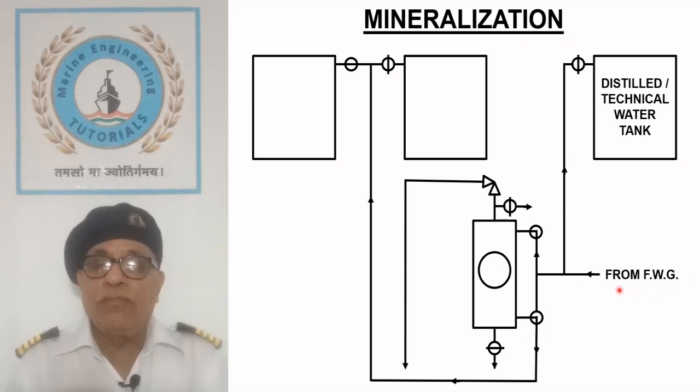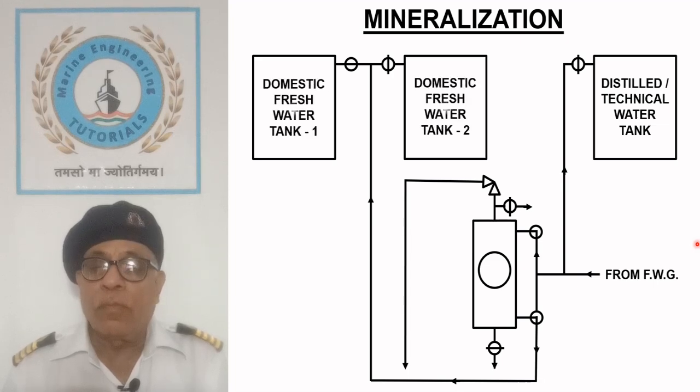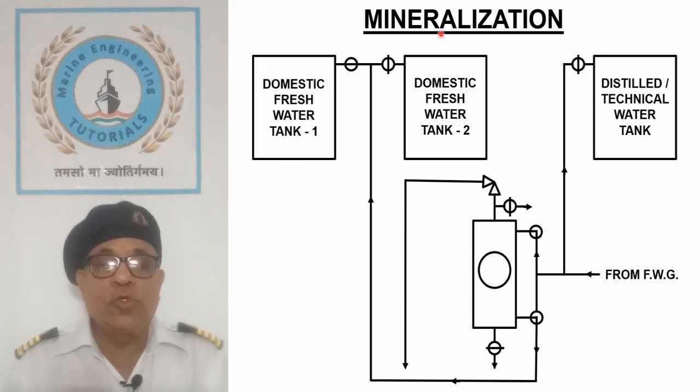Evaporated water is led to the distilled or technical water tank directly as it does not require any treatment. Cargo ships are equipped with two domestic water tanks and the sketch shows filling of number 1 tank.